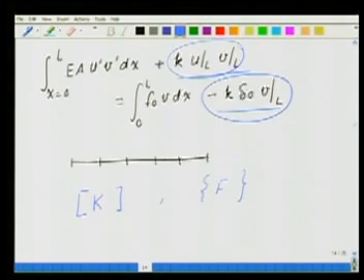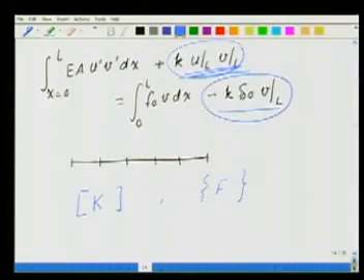Now you see that this condition K U at L V at L will be something that we have to apply to the stiffness side. So tell me in the stiffness for which phi, that is for which row, this part is going to cause a change. V at L, which V is non-zero at L? So this is true for only, for us, phi 6. So V at L is equal to phi 6, that is for the sixth equation. We will have to modify the stiffness term.